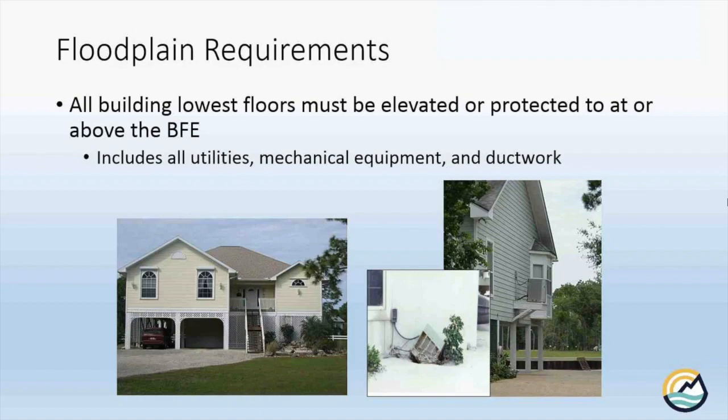So if you take a look there, that picture on the bottom left is a house that has been elevated up. Everything is open underneath. Really, anything that's damageable is up high. Same way with your equipment. The picture there on the far right, that HVAC unit that is up on that platform, when the water comes up, it's going to be fine. Whereas that smaller picture was one left flat on the ground and got destroyed during the flood.